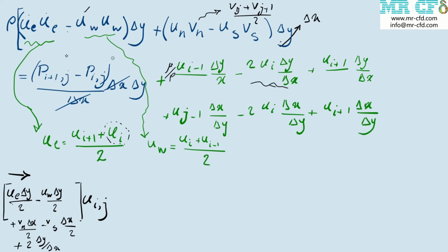When we divide the entire equation by rho, the last coefficient for u sub I, j, becomes 2 times delta x over delta y multiplied by mu over rho. On the right-hand side, for neighboring cell values like u at index I plus 1, j must add.